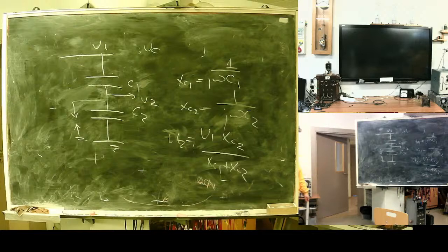They are capacitive dividers. These things are not precise. Capacitance is quite significant and depends on the outer temperature. But to detect whether there is voltage or not, it's enough. And for our case, voltage direction.